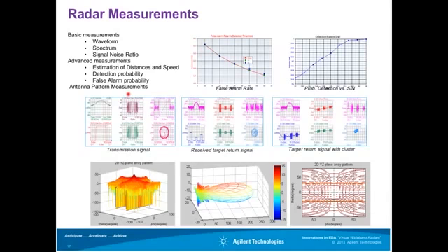Antenna pattern measurement are supported. Okay, you can plot 2D antenna pattern or 3D antenna pattern. In this way, you can monitor your phased array design to select TR module component to control the cost and get the calibration done.